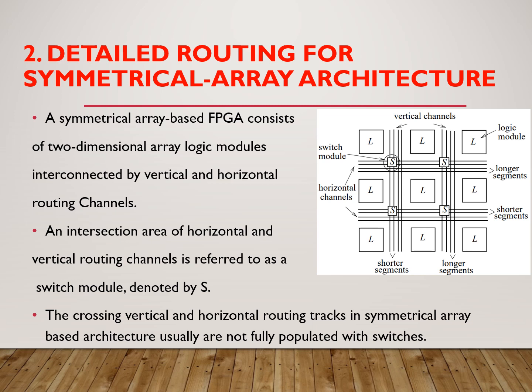So, in the row-based architecture, we have many switches for making the connection between two blocks. That will increase the delay. That's why we are going for detailed routing for symmetrical array architecture. Symmetrical array architecture means a two-dimensional array of logic modules interconnected by vertical as well as horizontal routing channels. See here, it is a 2D array of logic modules, right?